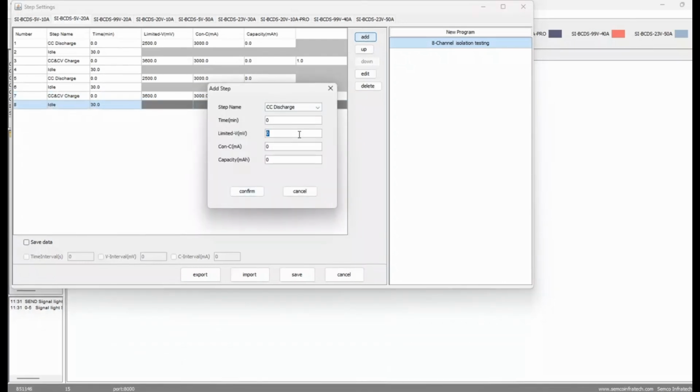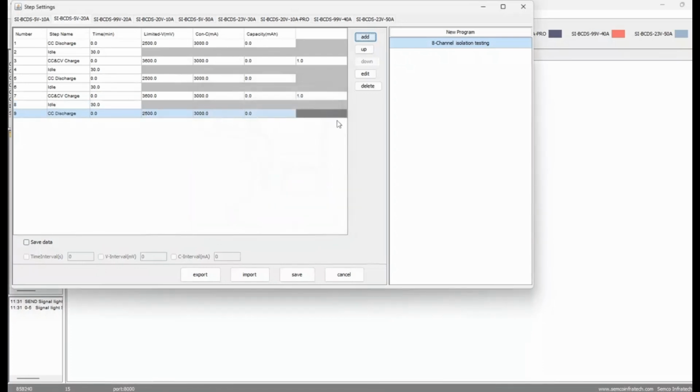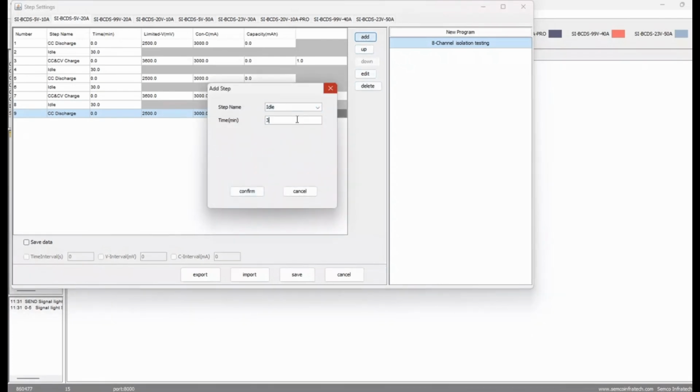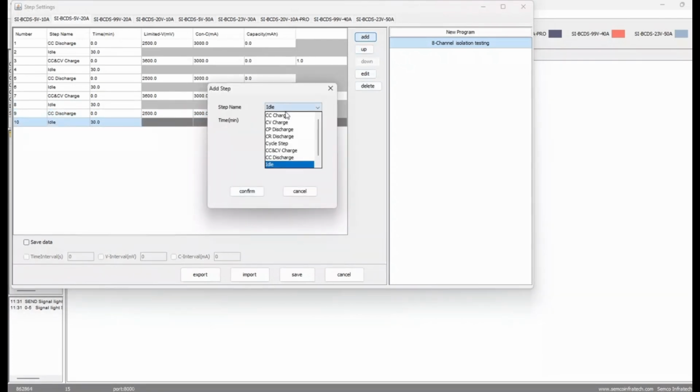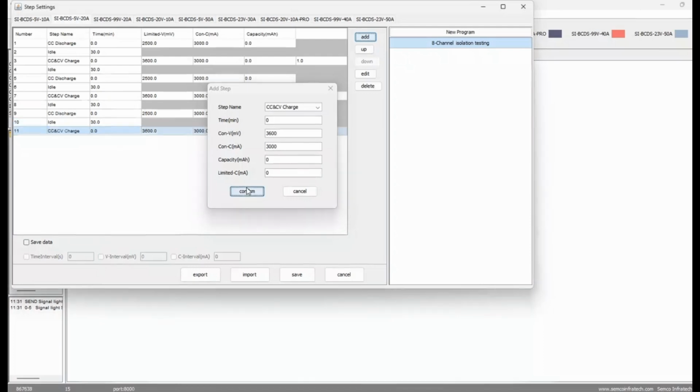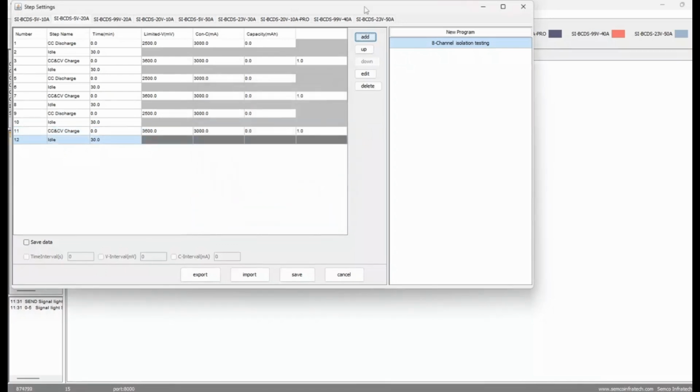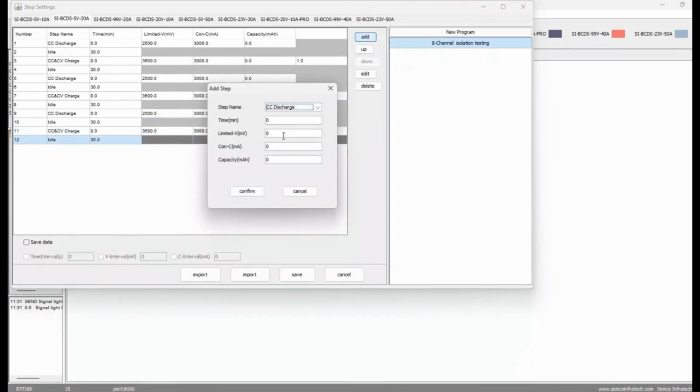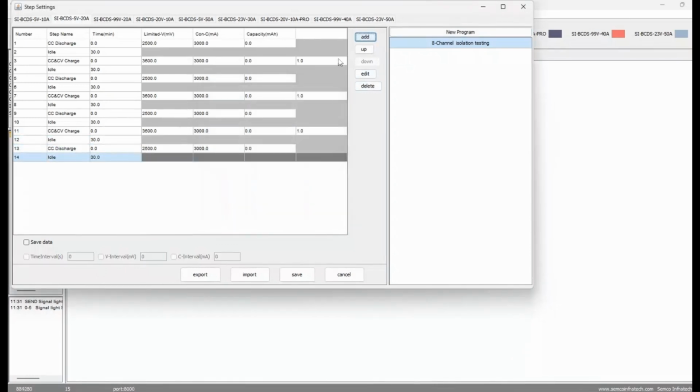For accurate capacity measurement and reliable performance evaluation, a single cycle is not sufficient. Therefore, the same sequence is repeated for a minimum of 3 complete cycles. Throughout all cycles, the charging current, discharging current, voltage limits, and idle durations remain the same. Repeating multiple cycles helps stabilize cell behavior and provides more consistent and reliable capacity results.